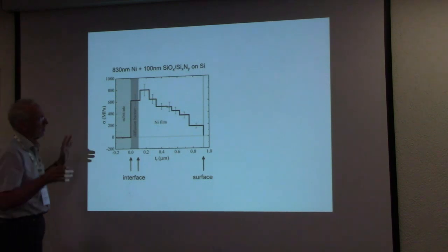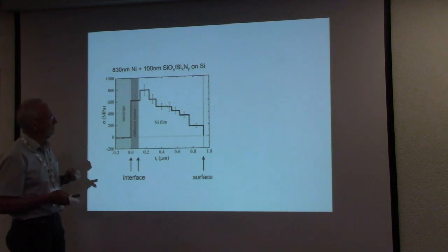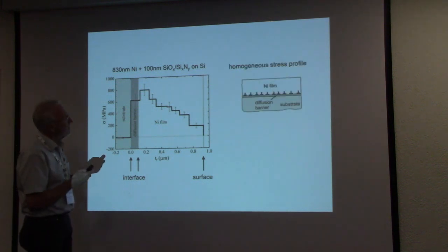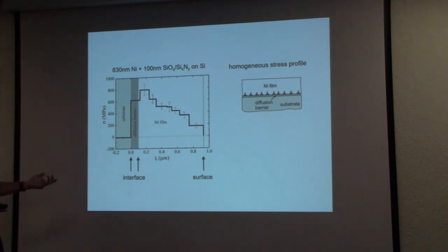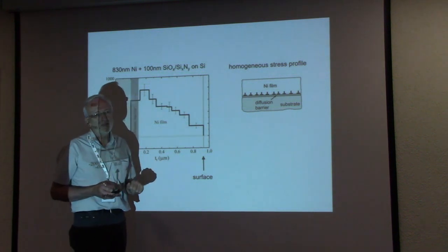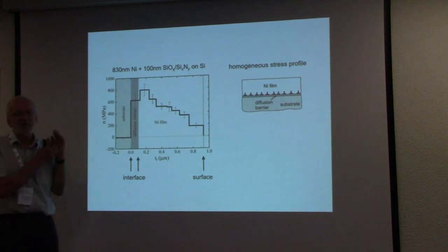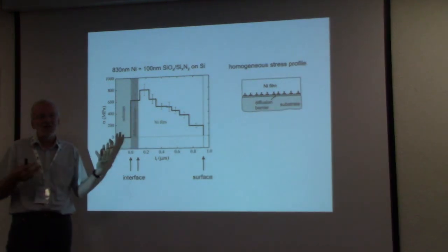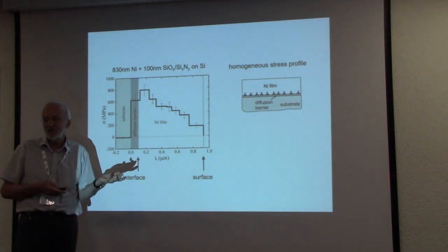Then there are usually large differences in the residual stresses, which are often simply a consequence that plasticity takes place, and dislocations on the free surface can run out, and on the substrate the dislocations are piled up, and this then causes gradients in the residual stresses.